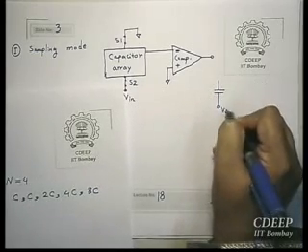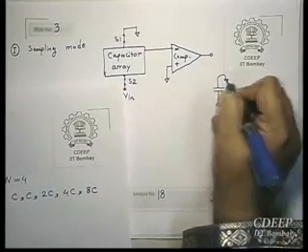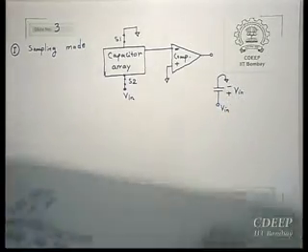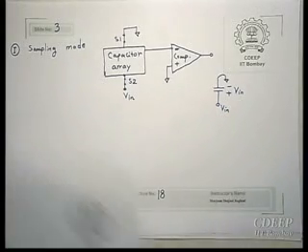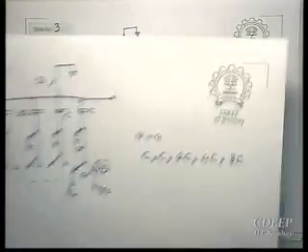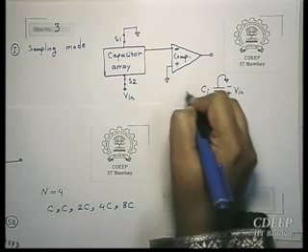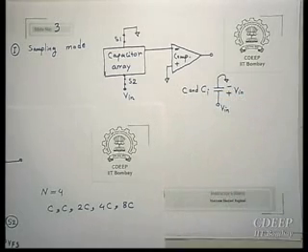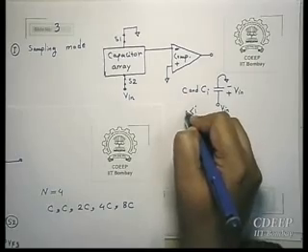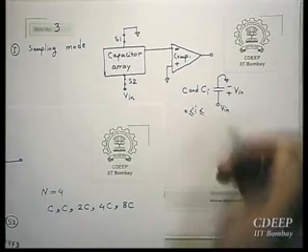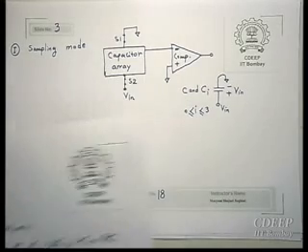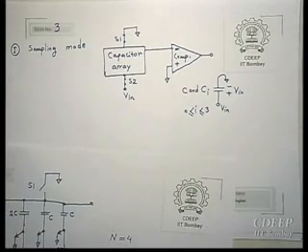This side is Vin, the bottom plate; the upper side is connected to ground. Therefore, you will have this polarity, Vin. Okay, so now you have sampled Vin on all capacitors. So this is eventually Ci, all capacitors. Ci and C, because we have one additional C. In our case, i is changing from 0 to, we have a total of 1, 2, 3, 4 capacitors, C0 to C3. So now all capacitors have sampled.